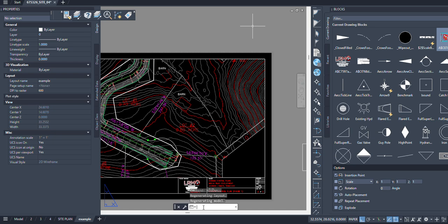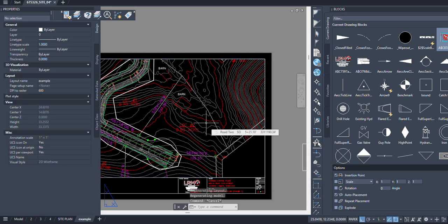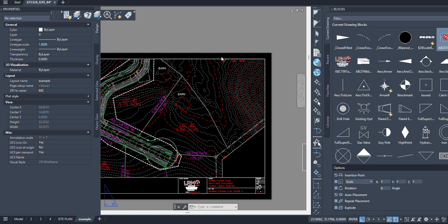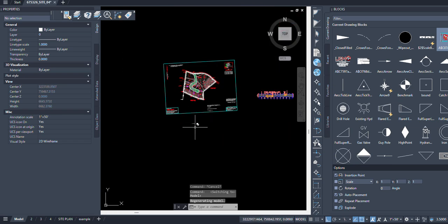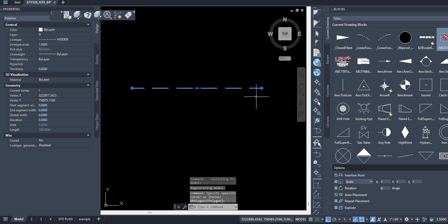So I turned PSLT scale off and lost the line. Turn it back on. So what I've noticed quite a bit is a lot of people don't know these rules, and they'll have a line that the line type's just not working out for them. It's not looking right. So the way they'll come in here and they'll start adjusting the scale.